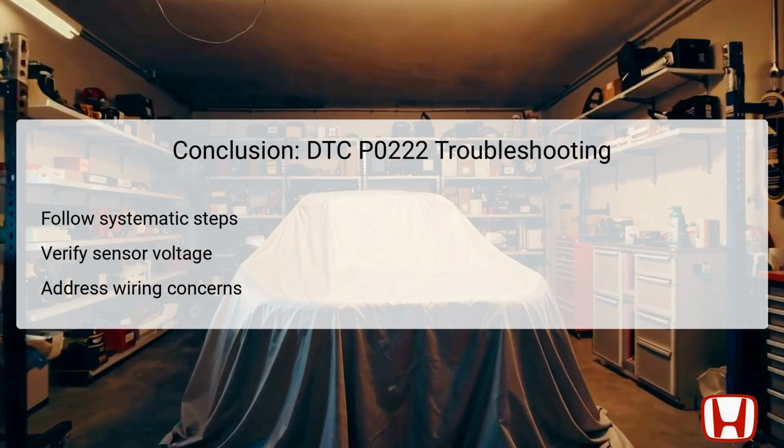Addressing wiring concerns, such as loose connections or shorts, is critical to resolving this error code effectively. Engage in preventive maintenance regularly to avoid future issues with the throttle position sensors. By adhering to these practices, you can maintain your Honda Accord's performance and reliability while addressing the complexities of DTC